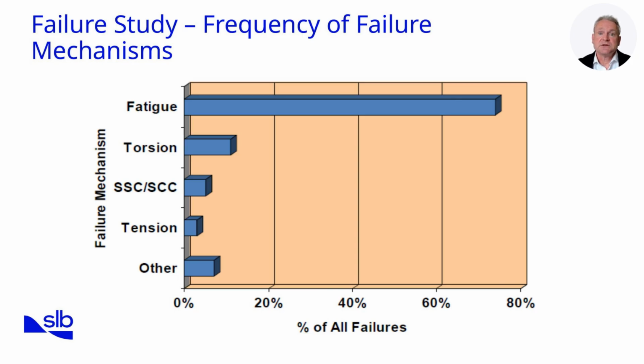Third is exposure to H2S, causing embrittlement. There are many large reservoirs, especially in the Middle East, that have H2S dissolved in the reservoir. This requires specially enhanced steel in the drill string and tubulars to provide some mitigation to this common problem.